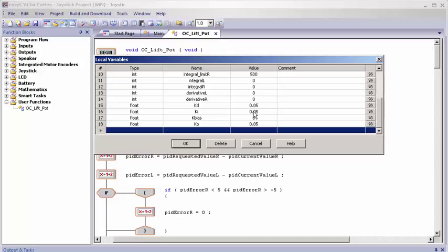On my little test lift, my test lift didn't have any weight on it, so these smaller values can help it lift up that small amount of weight that it's lifting. But on an actual robot, these values would have to be higher because of the amount of weight that's being put on them when you're moving around and carrying stuff. You would have to adjust these to your own robot's design. So that means you would have to do some trial and error and mess around with the values until you get what you want. And they will not always be the same like this. They will be different. So you'll have to test around with doing different ones.